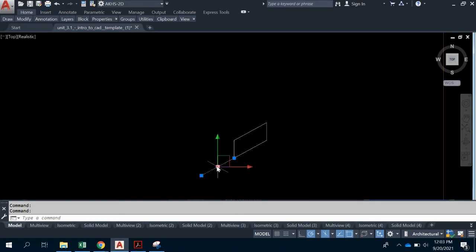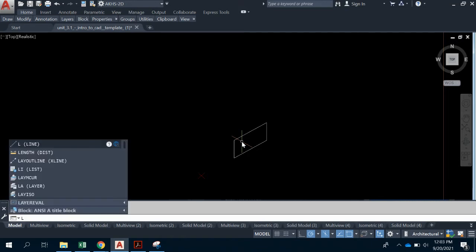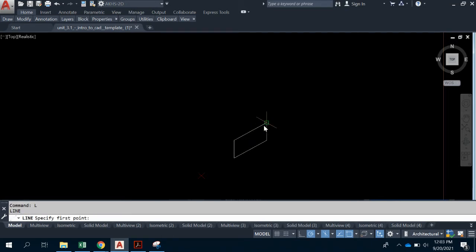Now I can left click here and press delete on your keyboard. Backspace and delete are not the same thing. So make sure you press just the delete key, and then we can start adding in some width from here. So this is depth and height really, and then we can start adding in some width. So I'm going to go with the L, enter, and then take each corner just like we would on the board and go up and to the left. So this distance here, let it snap to that green line, is 1.5.